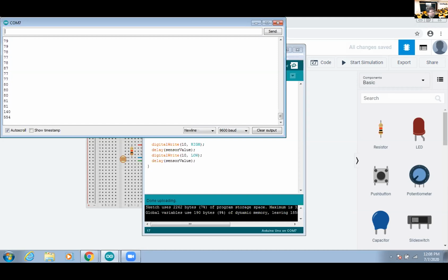That's the effect of the lighting around the photoresistor. So when it's completely covered, your value goes very high and your LED blinks slower. But when it's really bright around it, your LED goes super fast. And in the next class, guys, we will introduce some if logic so you can actually set up the evening conditions. We're going to call some values daylight, then some values night, and somewhere in between would be evening, when your light is going to come on. So for now we should close because it looks like you got it under control.